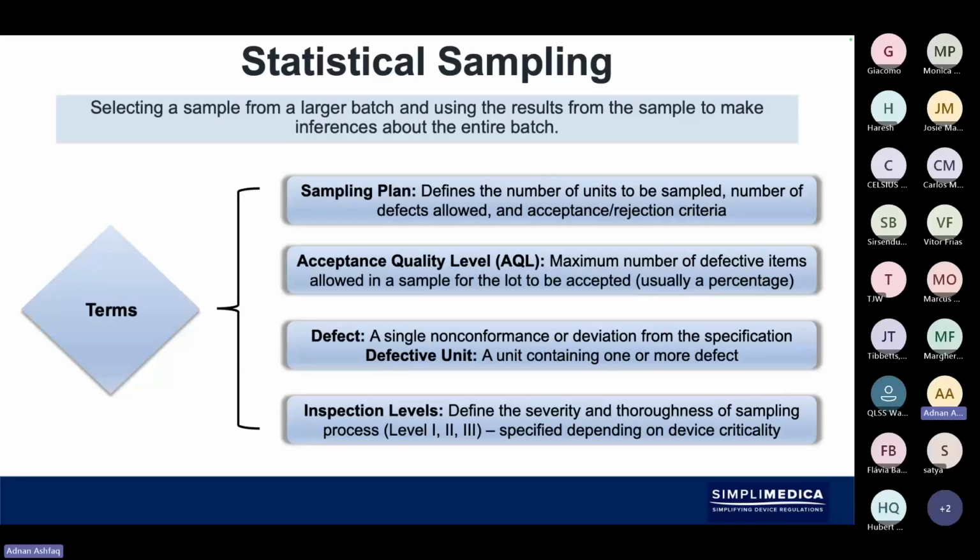Typically, these came from the military standard originally, and there are tables within the standard which, on a sliding scale, allow you to look at the lot size of the batch. And then based on the batch, using that sliding scale, you would define a number of units that you would take as samples during your manufacture and test for packaging integrity.